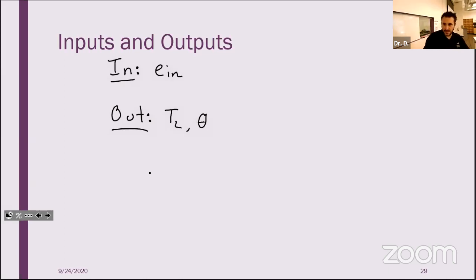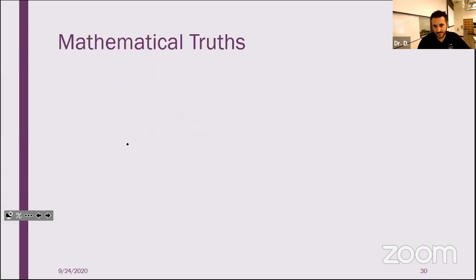All right, so far so good. Is everybody following me? Just general inputs and outputs, right? Again, what is the input? The input is the cause. What happens? I give some voltage. What happens as a result of that? My motor starts to turn, so I get some displacement. I also have some load torque that I need to overcome, so that needs to be part of that output. As we'll see, it's actually going to decrease the amount of usable torque that we have in our system.